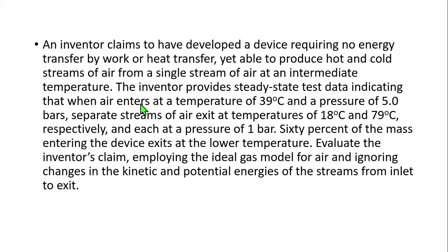So the question says that an inventor claims to have developed a device requiring no energy transfer by work or heat transfer, yet it's able to produce hot and cold streams of air from a single stream of air at an intermediate temperature. The inventor provides steady state test data indicating that when air enters at a temperature of 39 degrees Celsius and a pressure of 5 bar, separate streams of air exit at temperatures of 18 degrees Celsius and 79 degrees Celsius respectively.